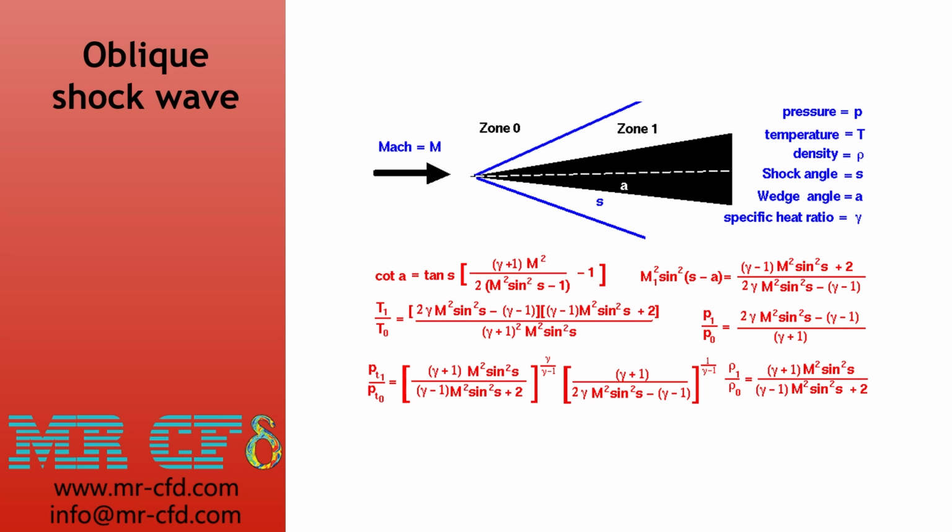As you see in this picture, we have some equations to calculate the pressure before and after the shock wave, and also we can determine the angle of the shock wave based on its Mach number and air density, which describes the altitude. So there are different angles related to this shock wave based on the cone angle itself and the Mach number, MN, called the normal Mach.